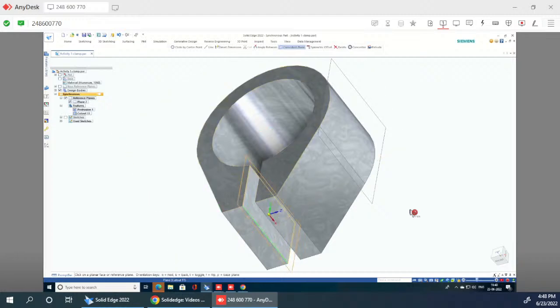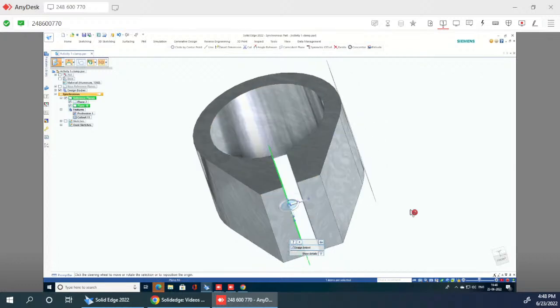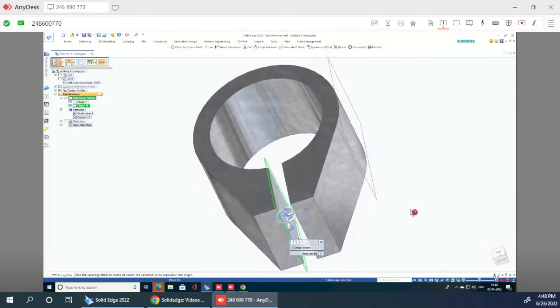We have to choose one plane to which we want it to be parallel. Then that plane we should move it to the midpoint, or even if you don't move to the midpoint, from there only you take it, no problem. Because I think he has taken from that point only, no need to take to midpoint. But I just wanted to teach you how to place the plane coincident with any point. Fine. So that's why I explained to you how to keep at midpoint.